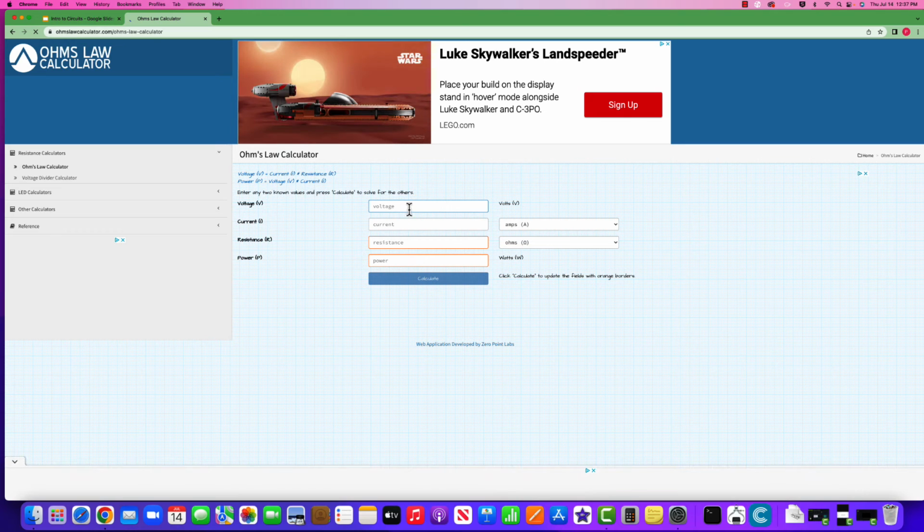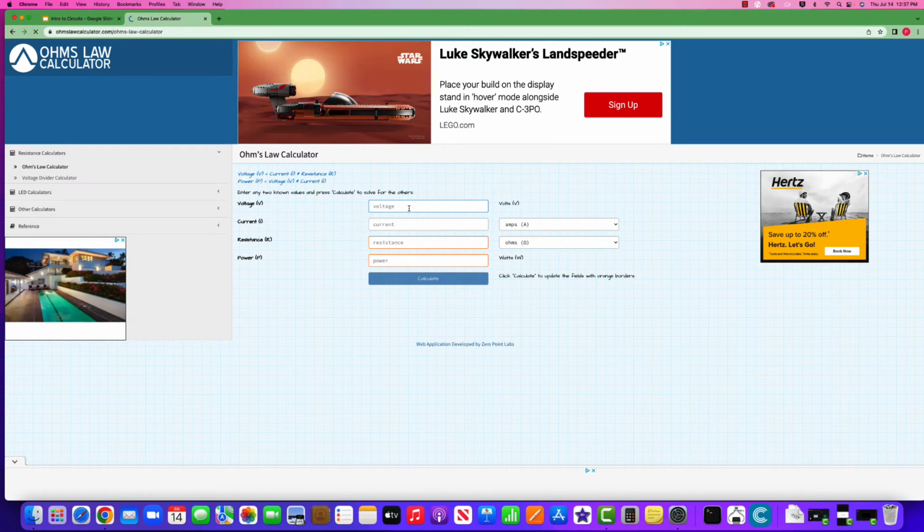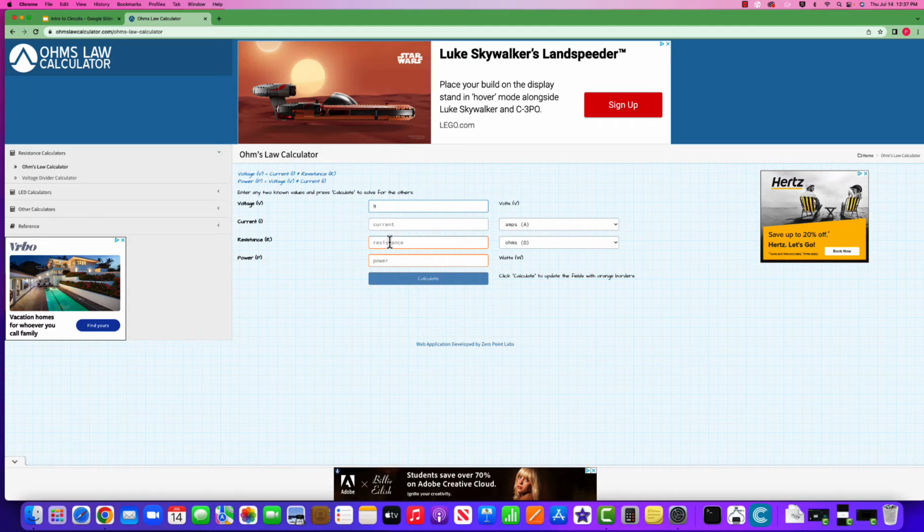Let's say you had 9 volts divided by 0.02. Calculate. So you would have 20 milliamps, 0.02, 9 volts, 9 divided by 0.02 would be 450 ohms.